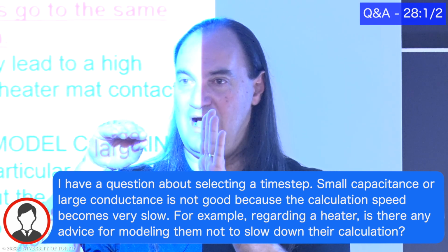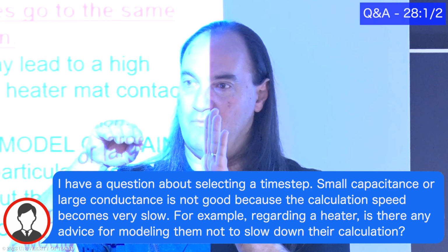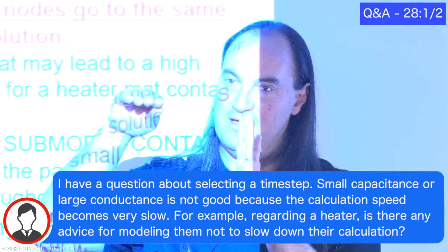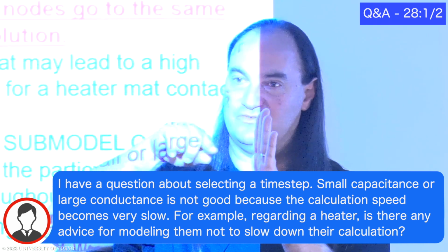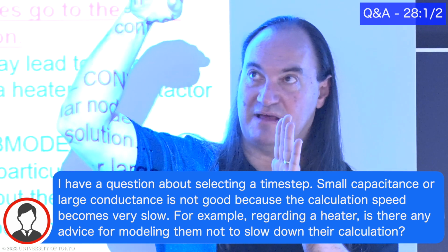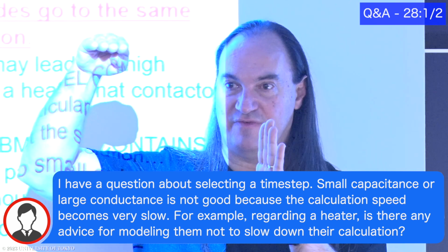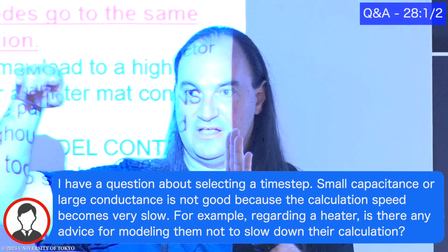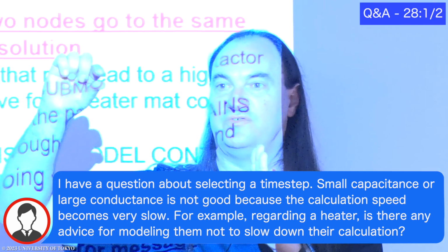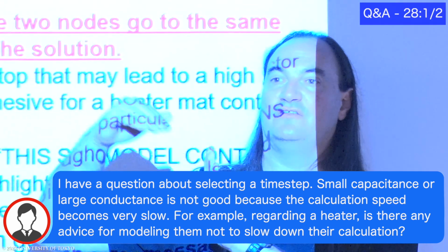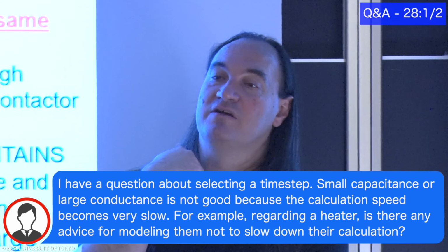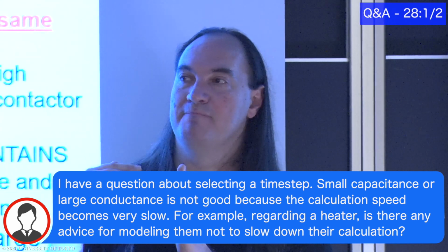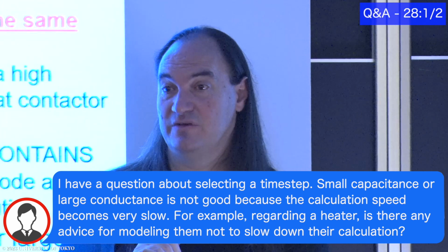If I'm a little bit too hot, decrease it slightly. And when I cross over the target, then I know that I've gone too far. Now let me decrease the amount that I adjust. So first I jump like this, then I jump like that. That's too much. Then I go half, then I go half, and each time I cross, I reduce the amount that it allows it to deviate from there. So that lets it get to a better convergence spot for PID heaters.